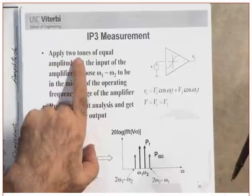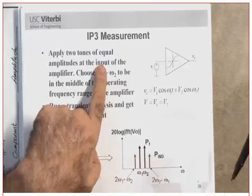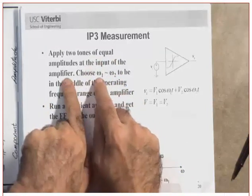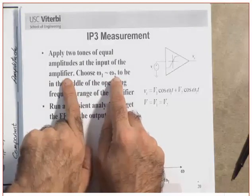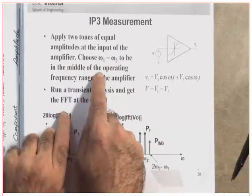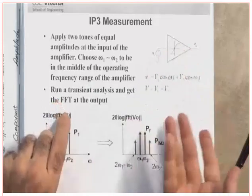You apply two tones of equal amplitudes at the input. Notice, by the way, we need to apply two tones. Otherwise, you are not going to get intermodulation. Apply two tones at the input of equal amplitude. Choose omega 1 very close to omega 2. The two frequencies are close to each other. Both of them are in the middle of the operating frequency range of the amplifier. What does that mean, by the way?